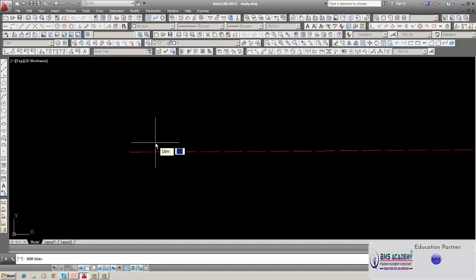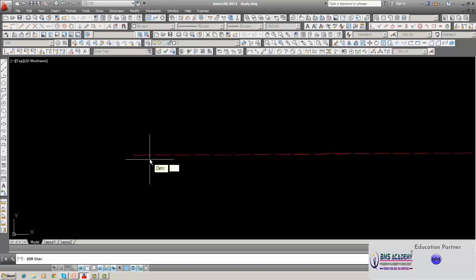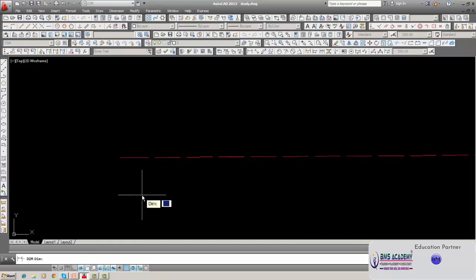So the distance from one dash line to another is about 6 mm, and on the actual print it is only 0.06 because we have reduced the scale. But that is very small, you cannot see whether it is a broken line or a dash-dot line or whatever it may be. So we have to distinguish it.